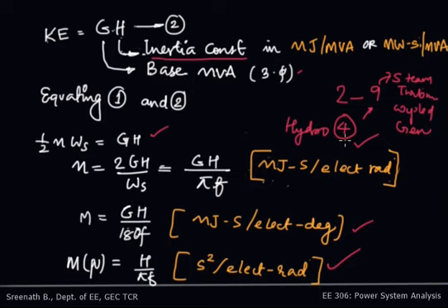Once your system fails, kinetic energy has to be stored in order to supply it during your required periods. In such cases where you have a failure of some of the systems, once an entire generator fails, that excess load has to be shared among all the other generators. So generators which have a larger inertia constant will have the responsibility to share a larger load. In such a way, the load will be shared among different generators. So this inertia constant is very important from that perspective.